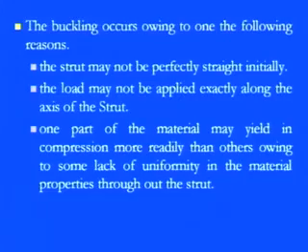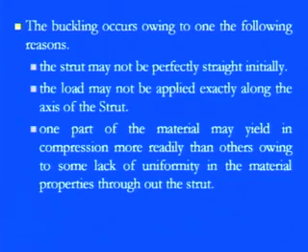Second, the load may not be applied exactly along the axis of the strut. As I told you, in the transverse direction, if the load is not applied exactly through the axis, like the compression we are talking about, they are not exactly on that particular axial line. As I told you, these stresses, compressive or tensile, are the normal stress components, and they have to be along a particular line. Because these are axial stresses, if they are not exactly along the axis of the strut, it will end up causing eccentricity, and due to the eccentricity we have a different kind of loading, which we have discussed already in the earlier chapters.